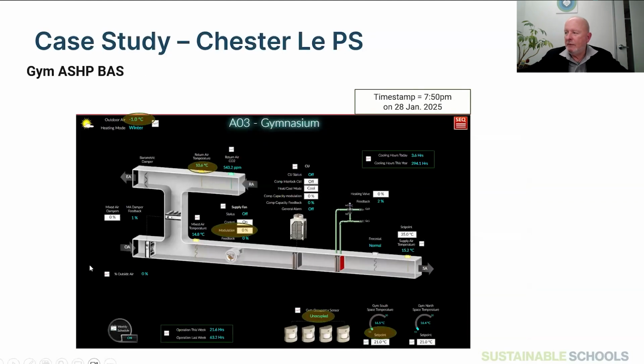And a few things we liked here. We like you got a variable speed drive on the supply fan, no return fan. But during unoccupied periods when you need the unit for heating, it's nice to be able to run at a lower speed and save a whole bunch of electricity overnight.